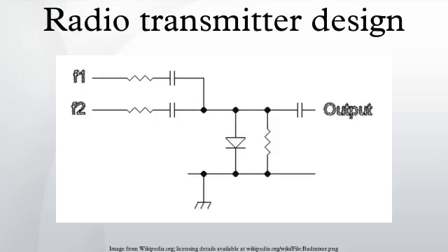Typically a transmitter design includes generation of a carrier signal, which is normally sinusoidal, optionally one or more frequency multiplication stages, a modulator, a power amplifier, and a filter and matching network to connect to an antenna. A very simple transmitter might contain only a continuously running oscillator coupled to some antenna system.